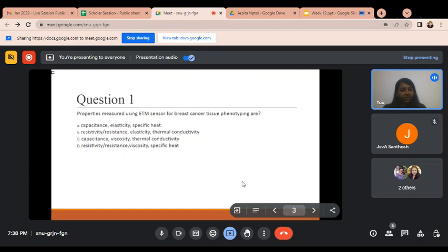In the development process, there is a chemical present. For the positive photoresist, there is a mask and chrome is present. The covered area will remain. Where the chrome is present over the positive photoresist, that portion is covered, and in the transparent area the UV rays come through to the positive photoresist. In that case, this positive photoresist becomes weaker.